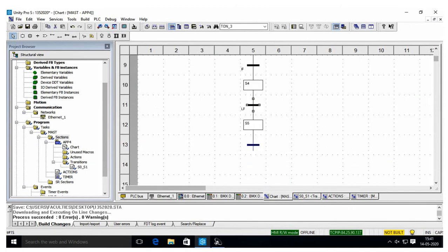Okay, so now I want to check for the condition. For that condition, I have to draw the alternate branch. Here you can see, this is the new one. You might not have seen. So this is the alternate branch. So I will put the alternate branch here. I'll put the alternate branch here with two transition conditions.